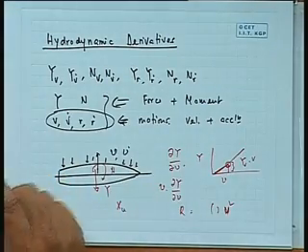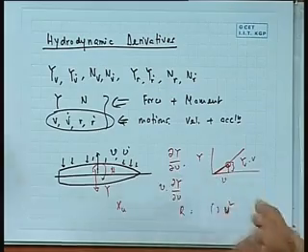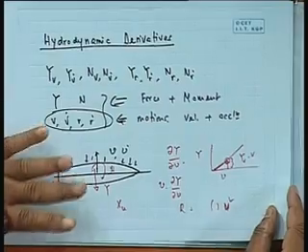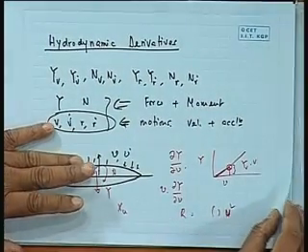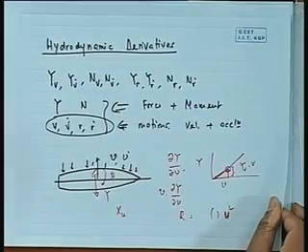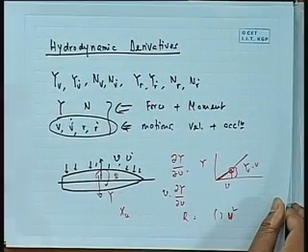We do not use the term derivative there because derivatives are supposed to be small numbers, but it is something similar to that. What we need to now do is to check one by one what would be the typical magnitude and what may be the typical sign, plus or minus, for these derivatives. We can find out by a qualitative study, which is what we will do now for some time. Which direction is Yv? That means, for all these terms, is Yv positive or Yv negative?